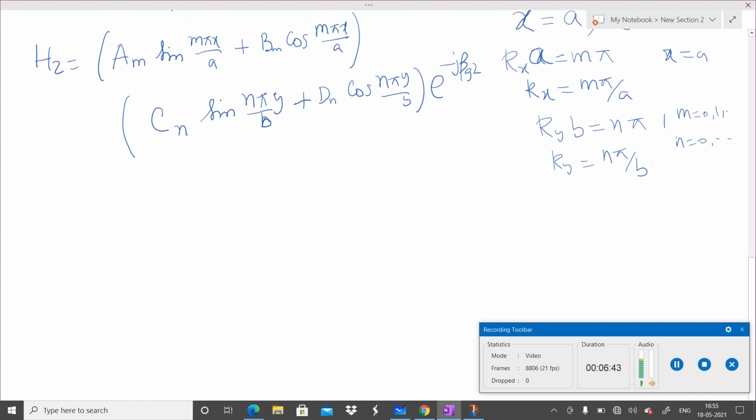Now this is the wave equation for one component, the magnetic field component in the direction of propagation. There will be other components also. Especially see, Ez is 0. Only when Ez is 0 is it called a TE wave. And since it depends upon m and n, what will be the different frequencies and wavelengths which are permissible to be transmitted, I will call it TEmn.